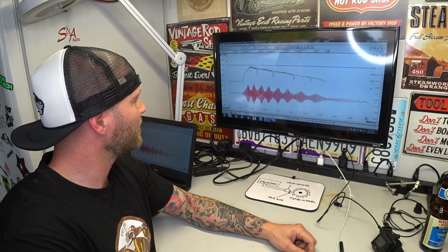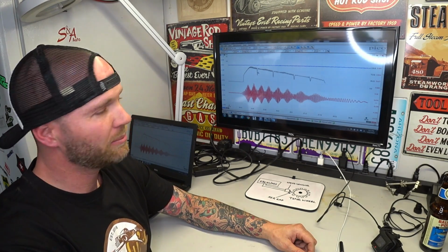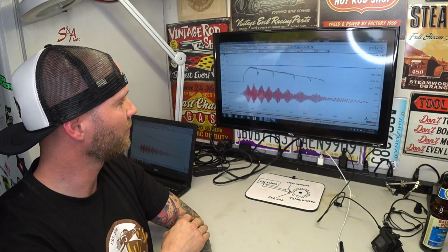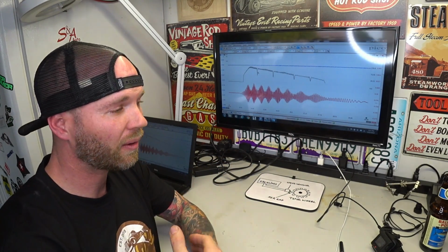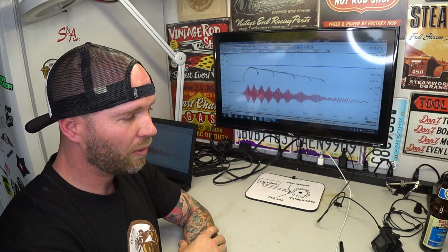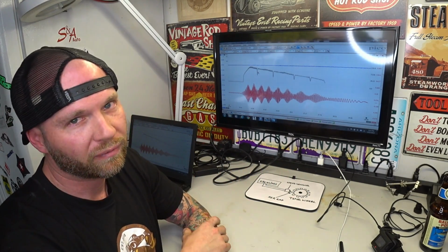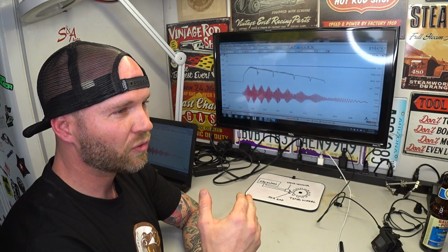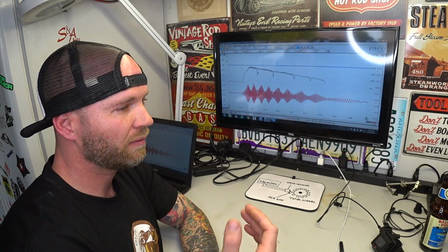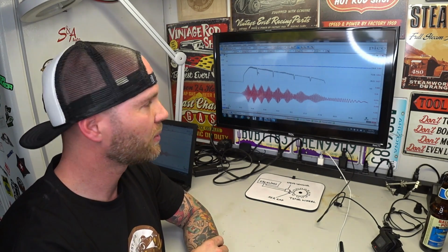this is what we're used to seeing on our scan tools. A PID like this, and it will usually be labeled in miles per hour. So as you speed up, the miles per hour will change. If you're going 45 miles an hour, usually all 3 or all 4 wheel speed sensors are going 45 miles an hour. And you can usually see when one drops out, and if you're going 15 miles an hour and one drops out and it goes to 0, obviously that's an issue.